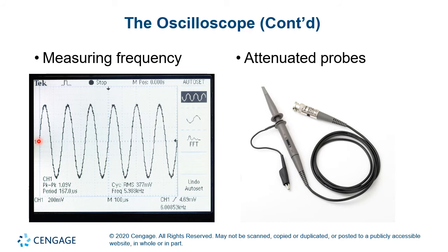So for example, if you have a 60 hertz cycle, there are 60 of these waves every second. On a scope, you can measure the distance from the beginning of the cycle to the end of the cycle, essentially the period of this sine wave, and using quick mathematics, you just find the reciprocal of that, and that'll tell you the number of cycles per second or the frequency.